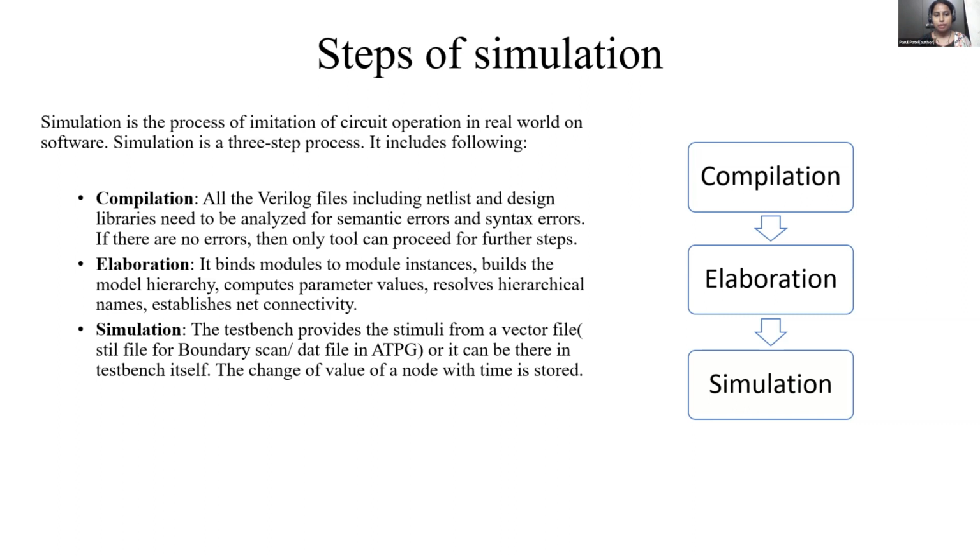So basically in elaboration, we are just building a high-level model of the design, which includes the test bench as a wrapper. Till now, whenever we elaborated or built a model, we only had the design. But here in elaboration, we will have a test bench also. Next, we have a build model of the design. Now that built model will be simulated. We will apply the test patterns to that model and check whether the expected output meets the actual output or not. And this checking is termed as simulation.